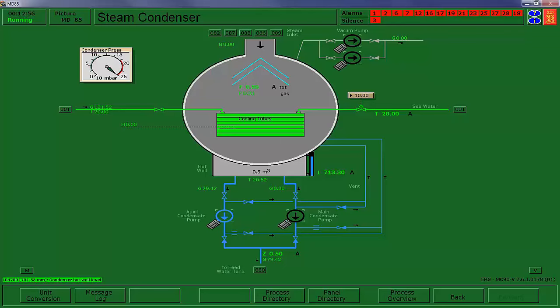One thing to realize on this too, this unit uses vacuum pumps rather than an air ejector. So we're not really worried about using the condensate in the hot well as a coolant. So we could pump that even dry if we wish to, but there's no reason to. And by the way, you notice that a small amount is led back as a reserve. Okay, so next thing we're going to do is supply heating steam to all the different services.